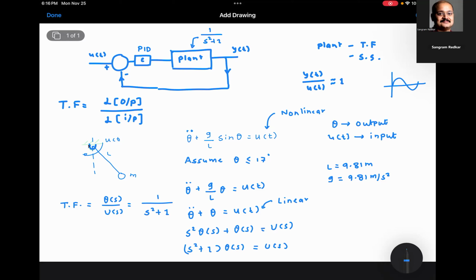And I want you to understand the assumption here. The original system is nonlinear, but I'm going to use a linear control. Understand, the nonlinear system behaves like a linear system when the output range is very, very small. Which means as long as that nonlinear system output is restricted within this small region, my linear control would work. Everyone understood this?